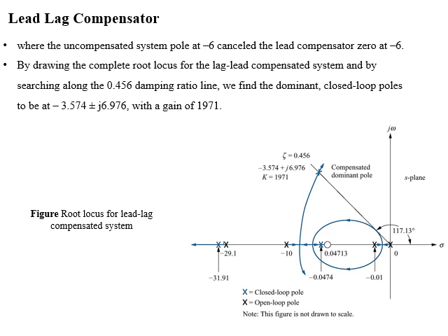Dear students, the figure represents the root locus for the lag-lead compensated system, where the uncompensated system pole is cancelled by the lead compensator zero at minus 6.